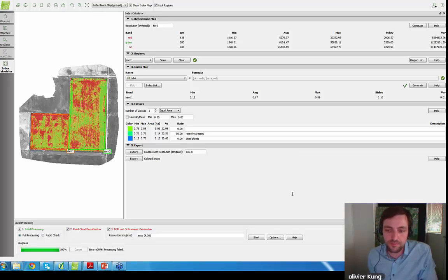Must the calibration target be photographed under the same illumination conditions as during the flight? Yes, the answer is yes. The goal of these calibration targets is to estimate the bias both of the sun and of the sensor. So you need to take them under the same conditions as during the flights. That's why you need to do this calibration at every single flight.